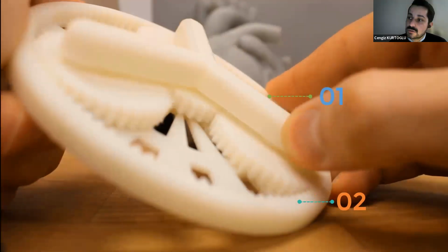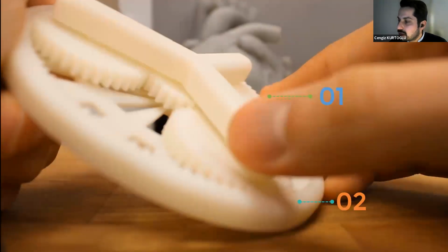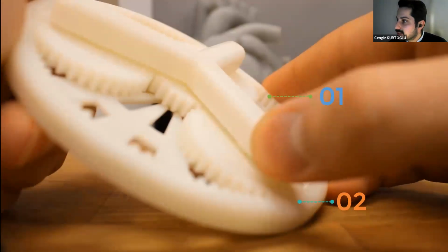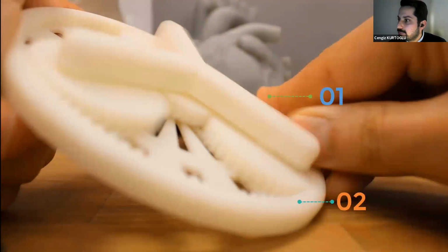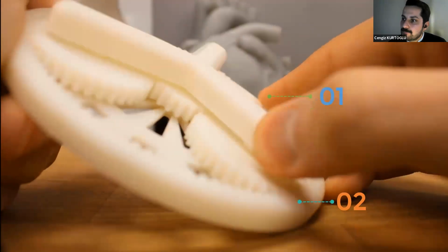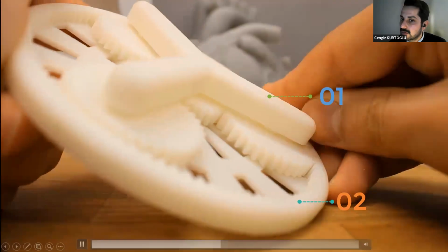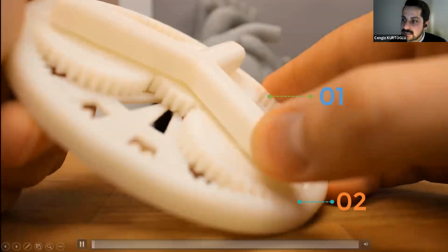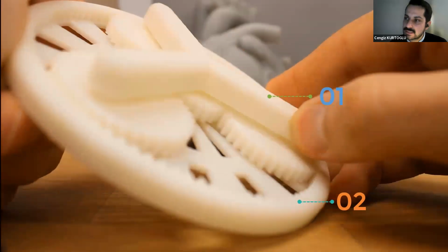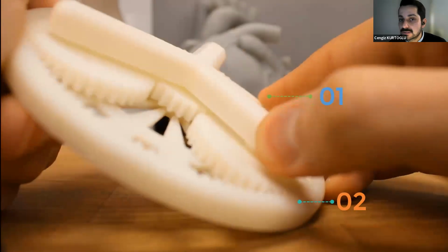It's important to use the material selection on your 3D printer, such as ABS, PETG, or other materials. It's also important to consider resolution and layer height to understand the tolerances or clearance, infill percentage, or print orientation, which is quite important.